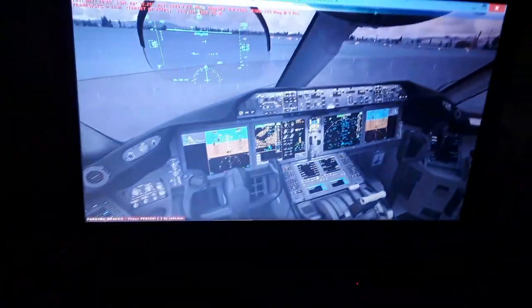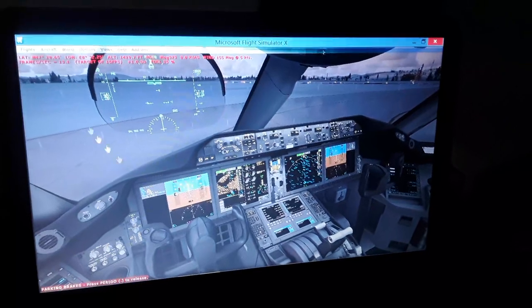And we're going to be aligned for a flight path for landing. We're going to have a pitch attitude like 9 degrees or less for touchdown, flaps like 25 or 30 degrees, and an airspeed 150, 160 knots. Also the landing gear down. So you will see how we're going to approach and land. We're going to have a complete flight plan or flight path or route for this aircraft. So you'll see what we're gonna do right now.